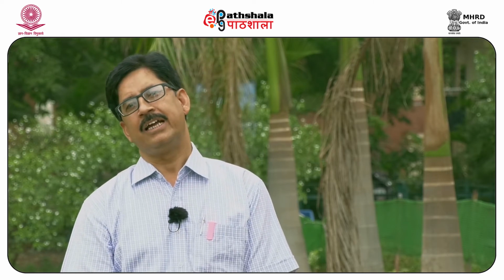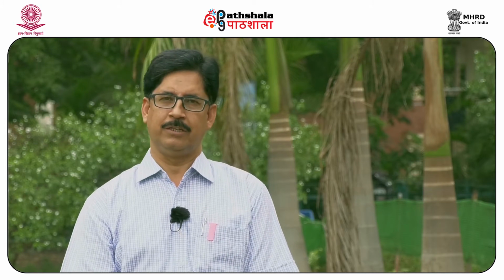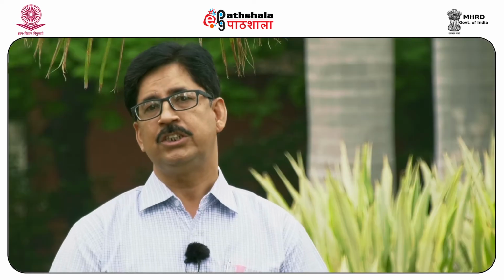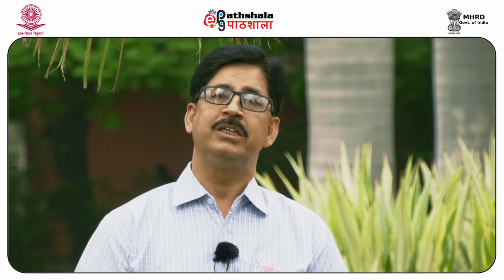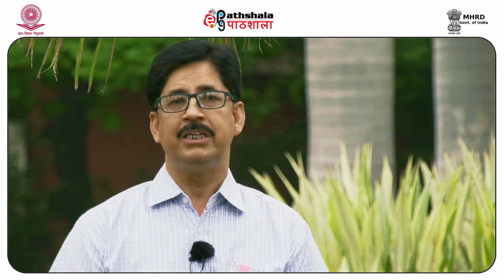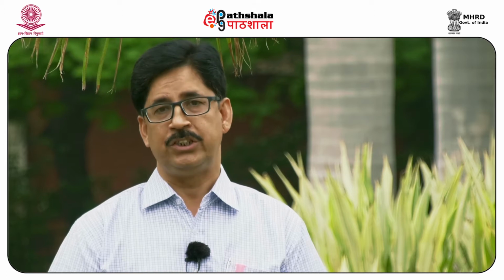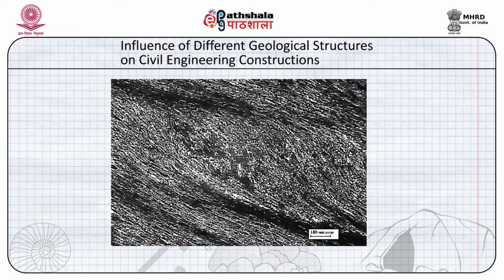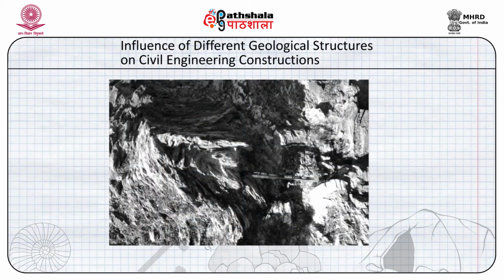the excavation or construction. Similarly, shear zones: after the joints, the most important deformation structure which we are going to encounter in the rock mass is the shear zone. Shear zones are partly brittle and partly ductile deformation. Along the shear zones, the character of rocks totally changes, and when it changes, you have weak rock mass along the shear zones.